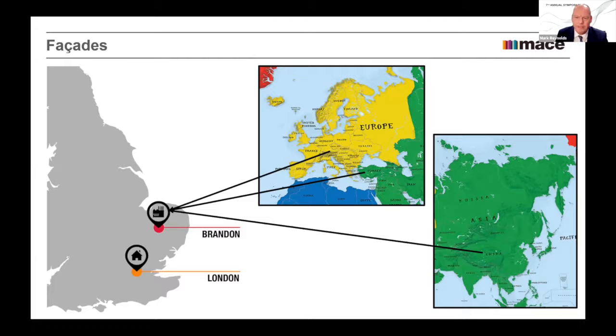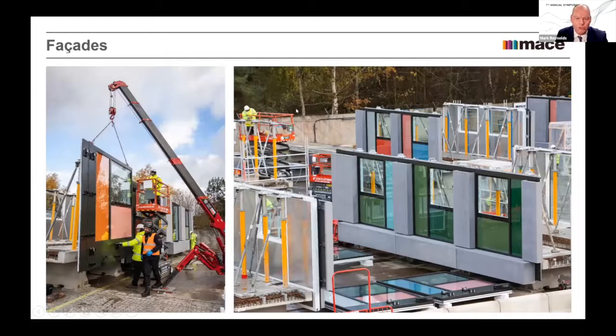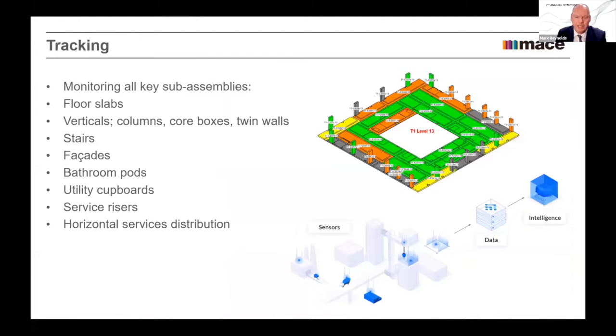So in the UK, there's a big agenda around levelling up and making sure work goes around the country. We erect the facade on the ground. As I said, it comes in packs, and then it's erected on the building on the ground, so thereby reducing the cost of any scaffolding, safety, and also people running up and down buildings.